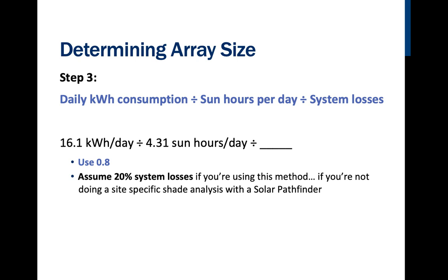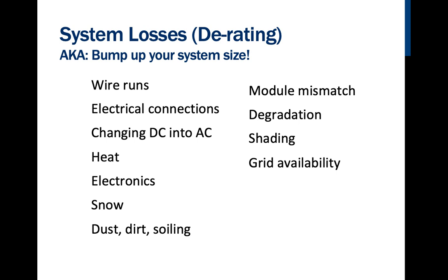So we're going to bump it up 20% by dividing this 3.7 by another 0.8, and I get a new number. And that number, by the way, is 4.66 kilowatts, or 4.7 kilowatts of DC array to make that 5,800 and some kilowatt hours on the AC side annually. So I'm going to overproduce in the summertime, underproduce in the wintertime, and it all evens out.